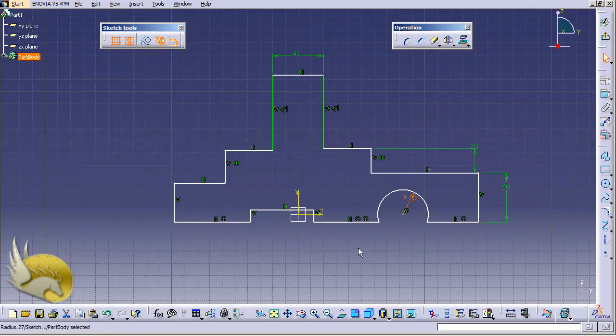Now I need to add some more constraints here. For example, I click on the constraint tool, select this vertical line here, and you can see that it adds some constraints like this. Click here, it is 10 millimeter, that's okay. And again, I want to select it by using the constraint tool and clicking on this. And this time you can see that it turns purple. That means that you are over defining your shape. I'm not going to over define, I'm actually doing something else.